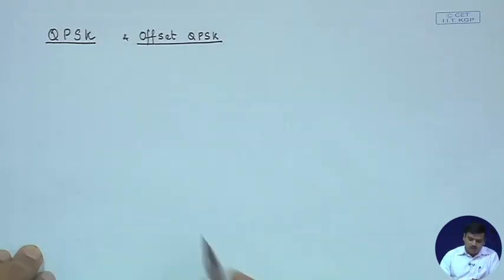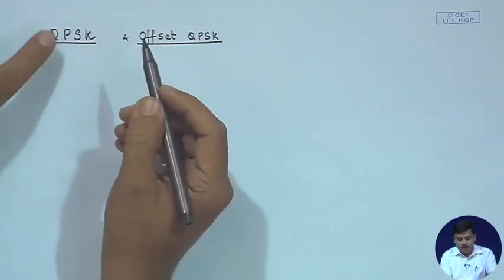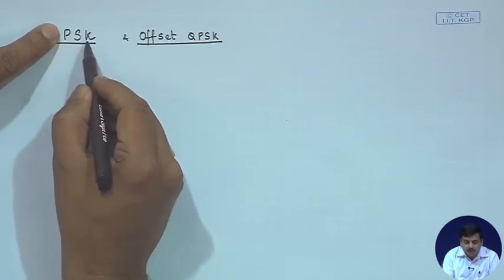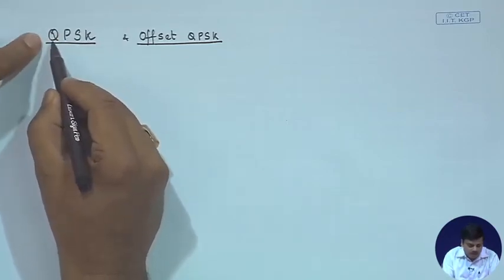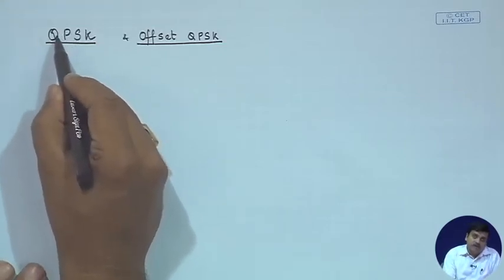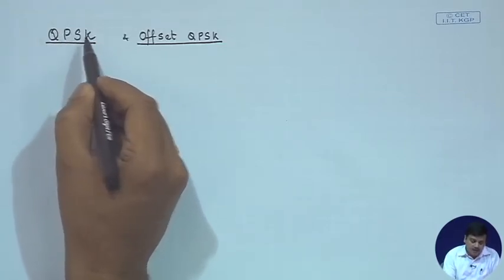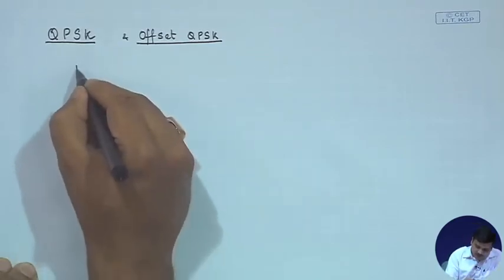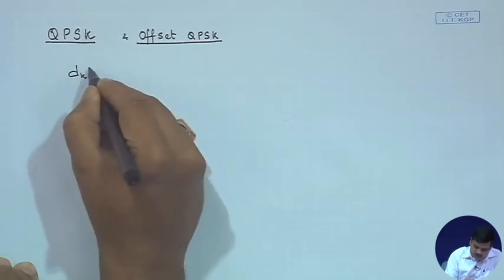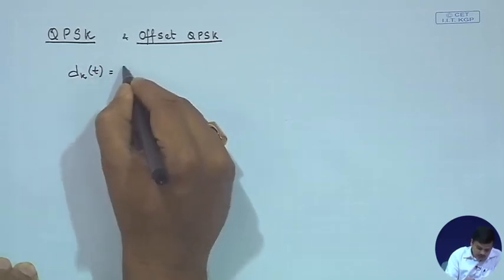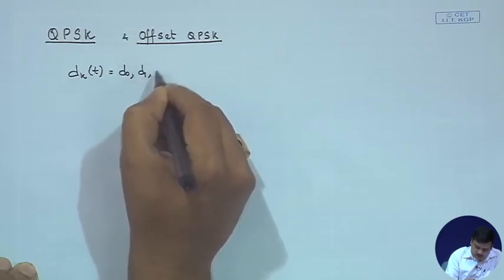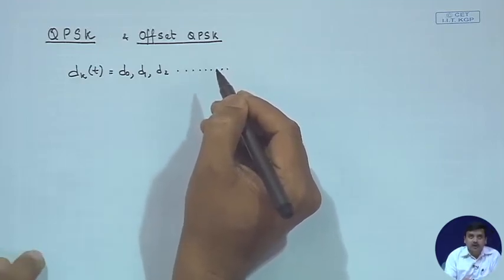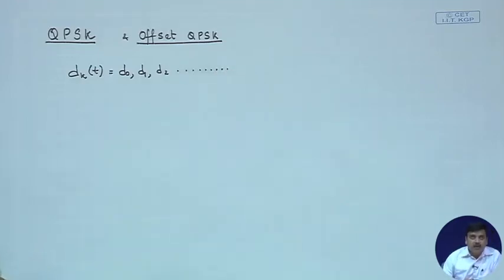Right. So, the QPSK, if we cover the Q, it is a PSK, that is phase shift keying. When we say Q, we mean it is quadrature, that means there are 4 phases. Right. So, in case of PSK, we typically have, let us say, the data sequence indicated by d_k being d0, d1, d2 and so on, which we were using so far as I1, I2, I3, I4.